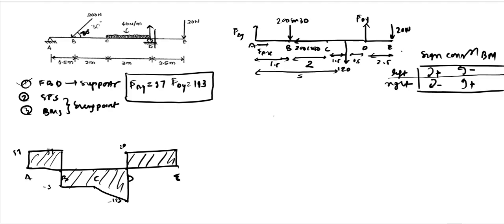So what we did in the shear force case is we always considered forces on the left side of the cross section, so we do not need to worry about the right side convention. But in this case, sometimes it will be easy for us to calculate the moment based on the right side forces, as you will see when we go forward in this question. So the right side convention also becomes important for this particular bending moment case.